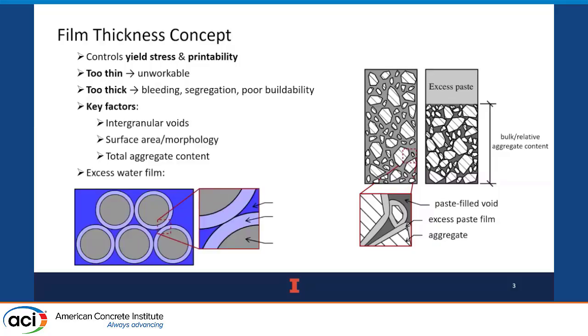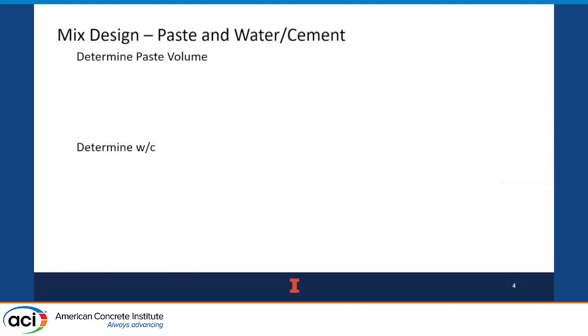Similarly, you can apply the same thing, and for us, no admixtures. So to tune your paste rheology, it's just your water-cement ratio or this excess water film thickness. So you can break it down into the same thing. And I know we would dream of getting cement to pack that nicely. It obviously does not pack like that. It's more of an analytical tool for determining paste rheology.